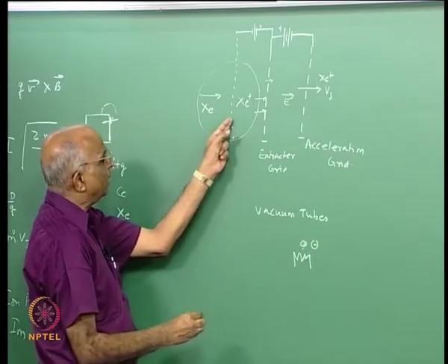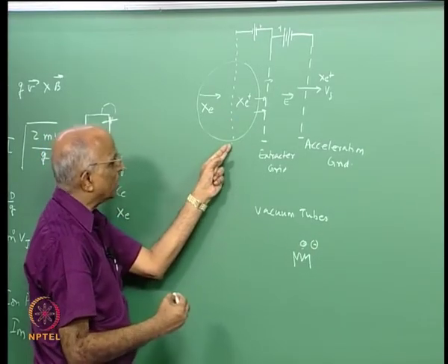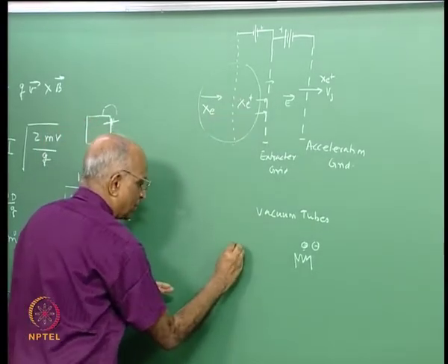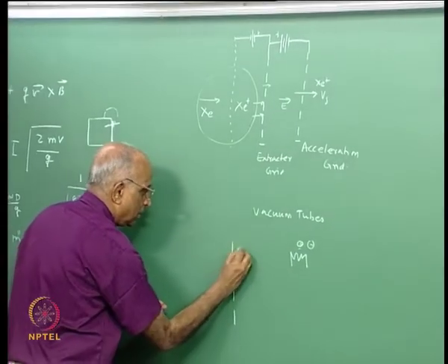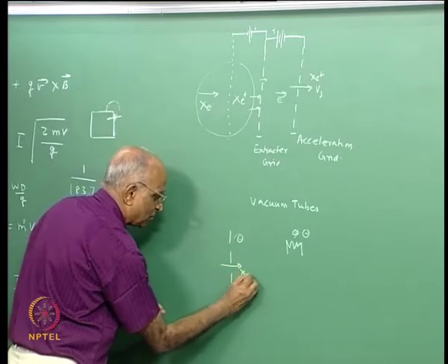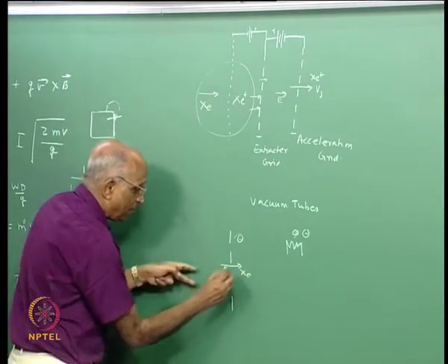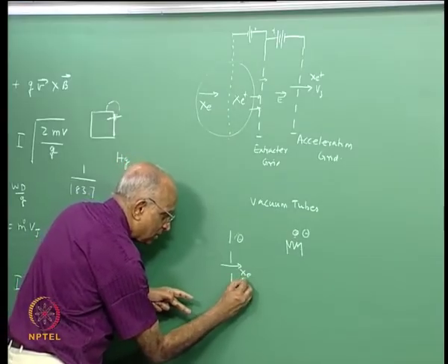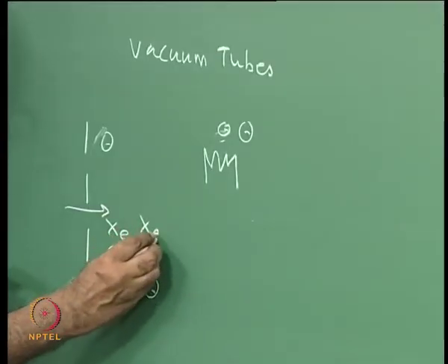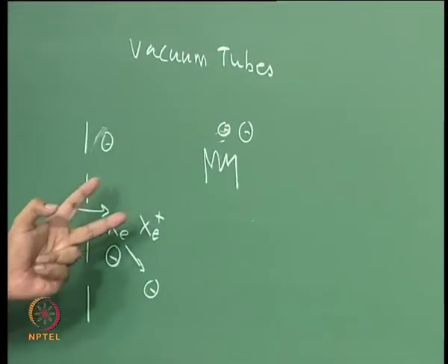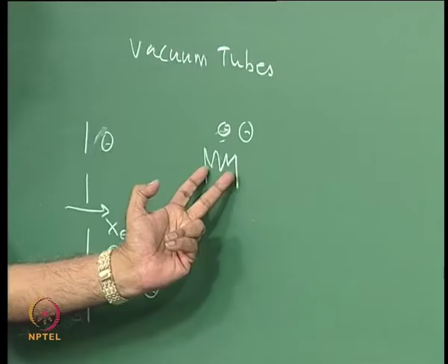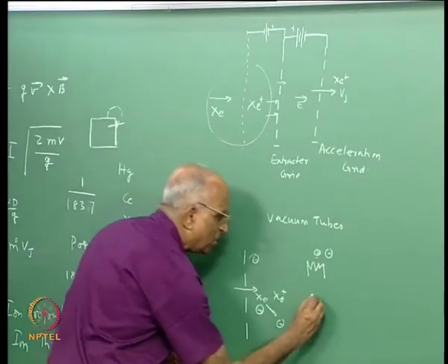Therefore if I could have a grid made of tungsten or even molybdenum for that matter, and I heat this particular grid, maybe electrons are generated from this grid, and these negative ions, when they hit against the flow of xenon gas which I am passing through this over here, the xenon ion, neutral xenon ion, is hit by a negative charge, and this fellow knocks off one more electron over here, makes the xenon positive, and this is how I could create it using a sort of a resistor which is heated, which I call as something like thermionic emission.